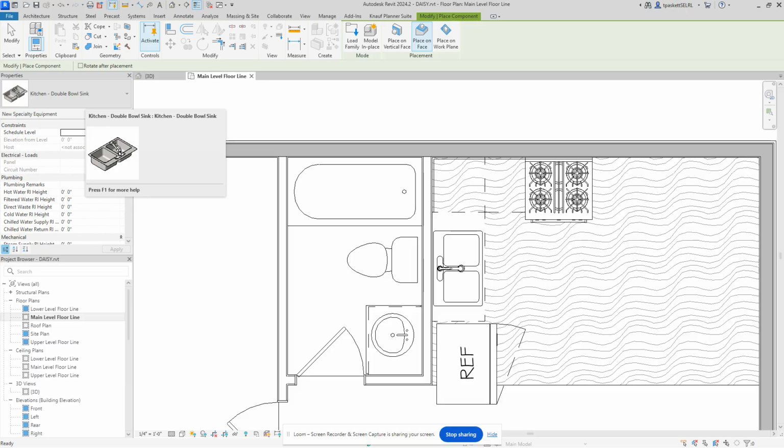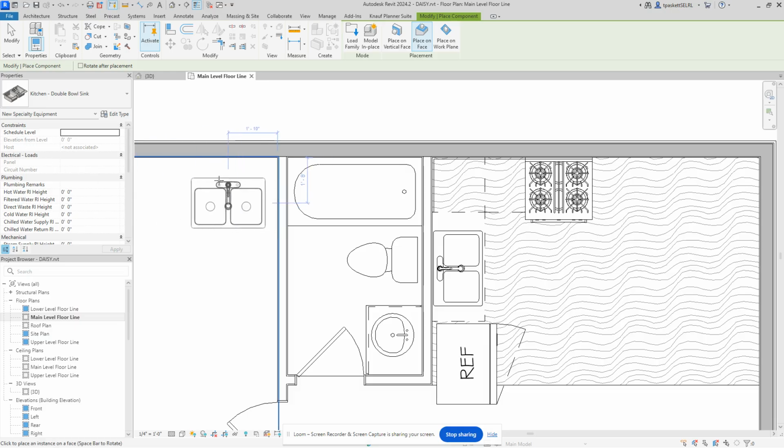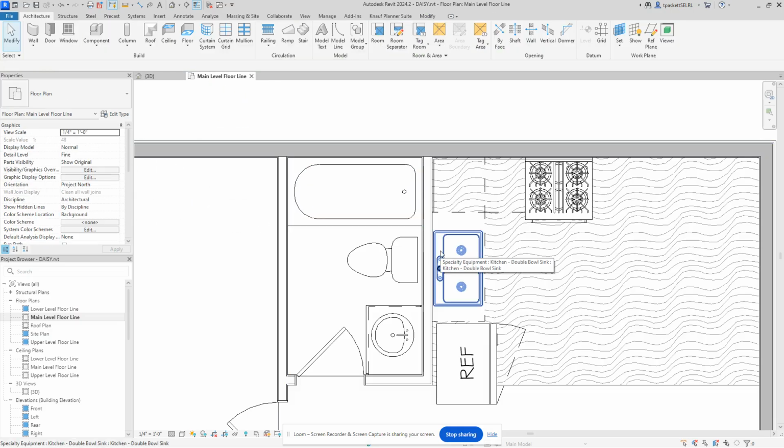Okay, upper cabinet. And then get rid of the shirt tails now. The upper cabinets are, get back over here. Okay, we don't have a lot of room to put an upper cabinet in. We're gonna do it anyway. We'll put two in. I think we can get two of them in there. When you place cabinets that are on the wall, there has to be a wall. So a lot of times when you're doing a design, they may have an island or a peninsula, and they want the cabinets over it. You gotta make a wall that hangs from the ceiling in order to place them.